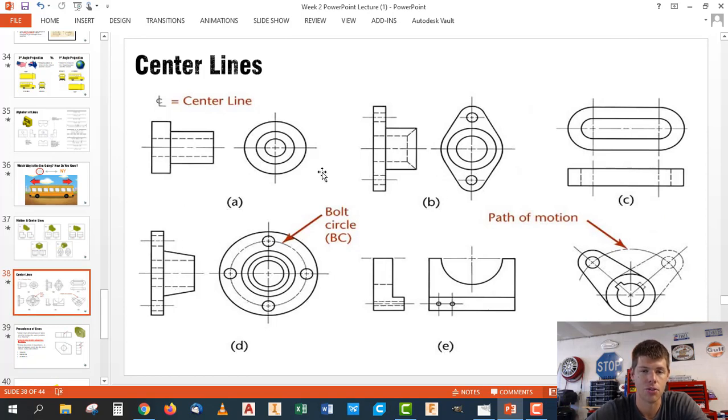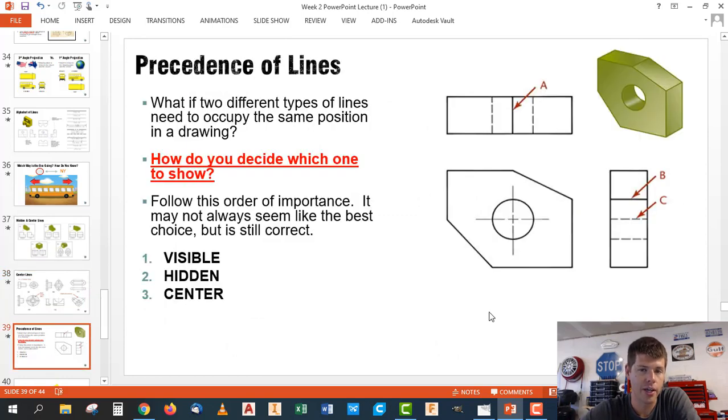Look at all the hidden lines in these drawings and look at how much additional information that passes along to the viewer. If you take those out, you're basically withholding information, and it makes your objects very difficult for people to understand. So these line types are important because they allow us to share information with people in a most easily understood format. The trick is that as we have these different line types we're trying to balance, sometimes they want to overlap with each other. And we're going to see some examples of that as we go through and try to draw some of these.